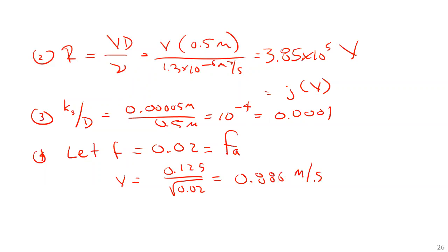meters per second, and we've been maintaining consistent dimensions. Remember, we've already done this problem 3 times. We should have had a friction factor of 0.0152. So I know 0.02 is wrong. You should know 0.02 is wrong. We can calculate the Reynolds number then. And the Reynolds number is equal to 3.41 times 10 to the 5th. Again, we just use the equation up above to calculate it.